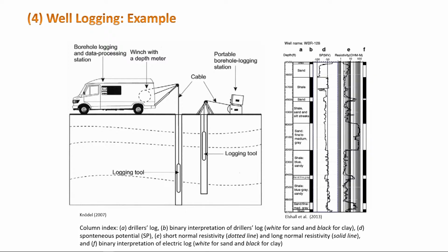So as the driller was recording his rock, I was also doing my homework and recording the same. The driller will tell you, now we are at 1 meter, now we are at 2 meters, 3 meters, 4 meters, and I was recording this, I think every few centimeters. Not only was I recording this, I was taking samples. I had plastic bags and I would take the sample material, put it in and mark it with a marker. I'd say this was at 30 centimeters, this was at 50 centimeters.